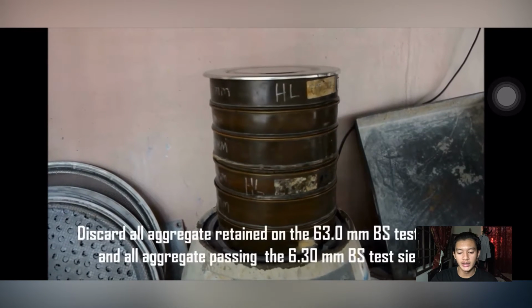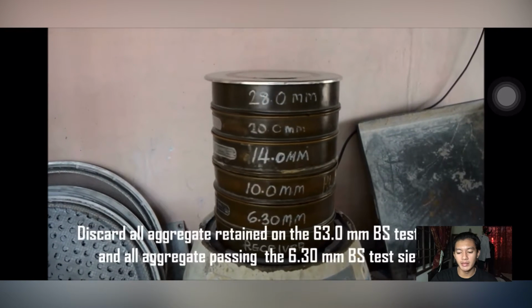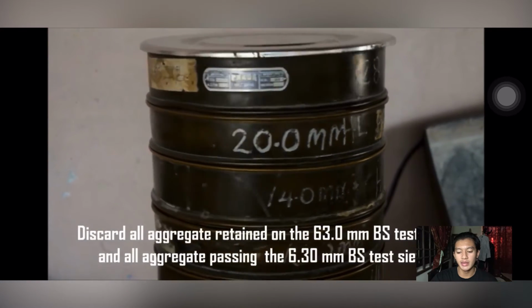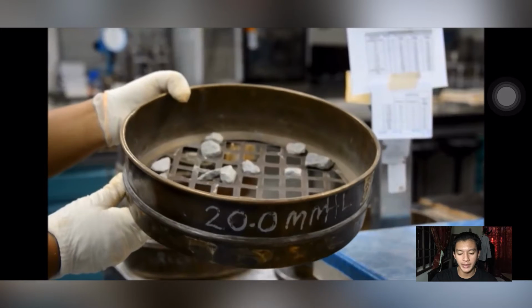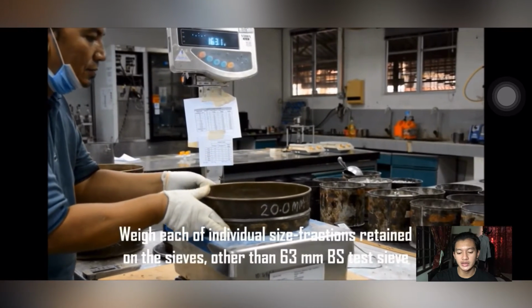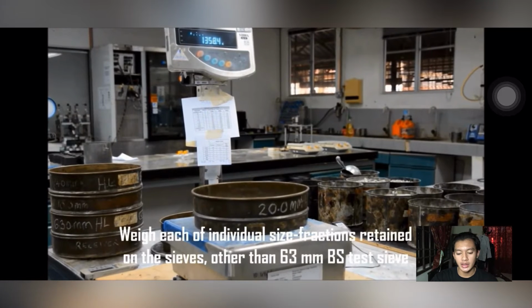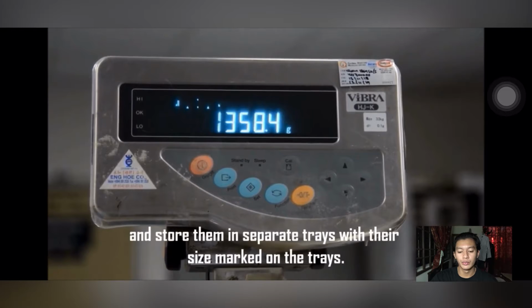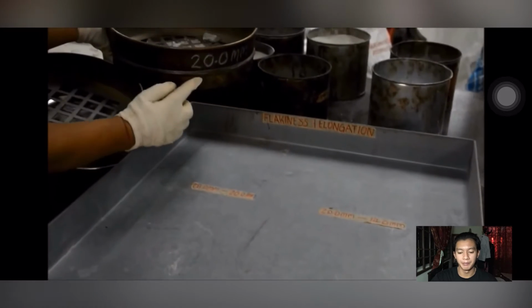Discard all aggregate retained on the 63 mm BS test sieve and all aggregate passing the 6.30 mm BS test sieve. Weigh each individually sized fraction retained on the test sieve, other than 63 mm, and store them in separate tray with their size marked on the tray.